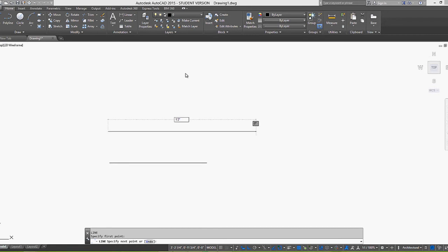So that dash is really optional. Okay, I can just say 1 foot, no dash, but 2 inches, and have it be the same. So again, hit enter, 1 foot 2 inches, enter, and then hit enter or escape to get out of that command.